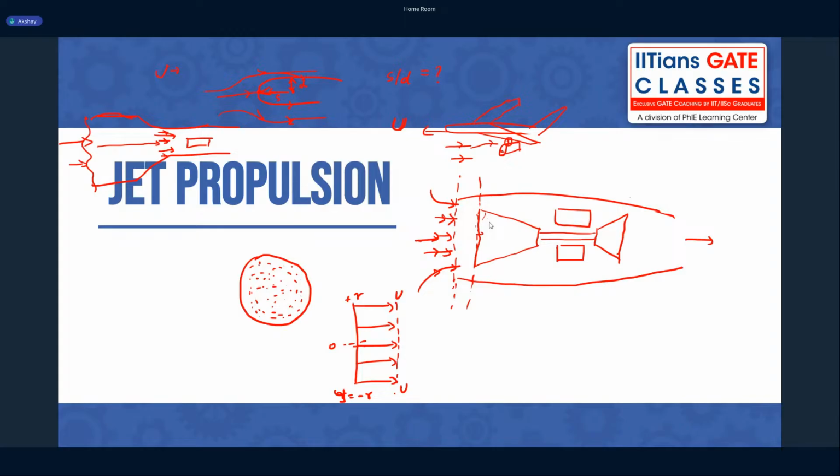Think like this: you are getting zero velocity at certain parts, 50 meters per second at certain points, and 100 meters per second at certain points, and that flow is entering the compressor. We cannot expect the compressor to behave in an optimum fashion, right? So we have to make sure that from root to tip, the blade of the compressor sees the same velocity. That is the whole idea. So all these disturbed flows, we are making uniform through an intake duct. That is the primary purpose of designing an intake duct.